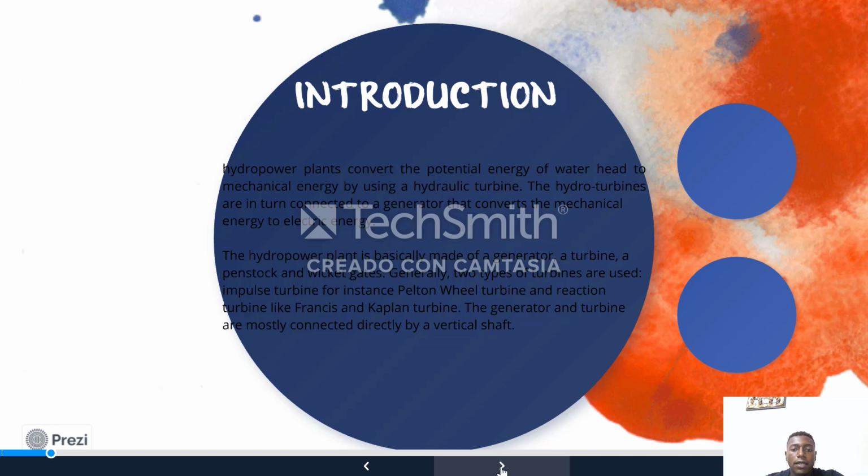The hydropower plant is basically made of a generator, a turbine, a penstock, and wicket gates. Generally, two types of turbine are used: impulse turbine, for instance the Pelton wheel turbine, and reaction turbine like Francis and Kaplan turbine. The generator and turbine are mostly connected directly by a vertical shaft.